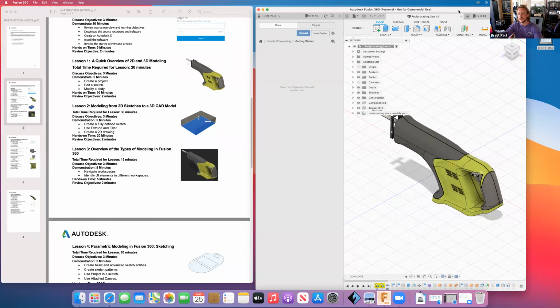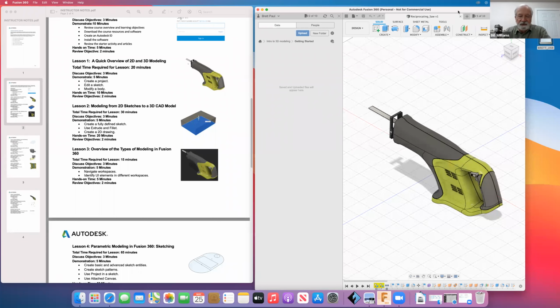You would have to either be drawing in 3D space, which I think you covered in lesson 3, or you'd have to finish the sketch and then create a new one on that other plane before you could sketch on that new plane. Okay, yeah, that sounds right then.